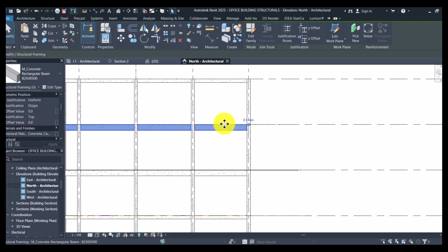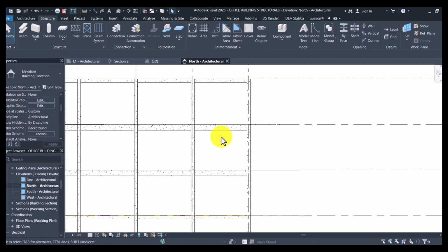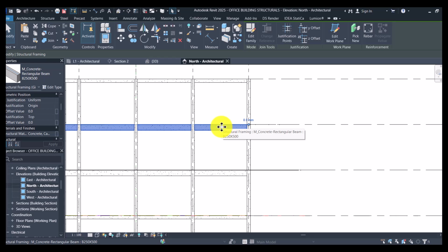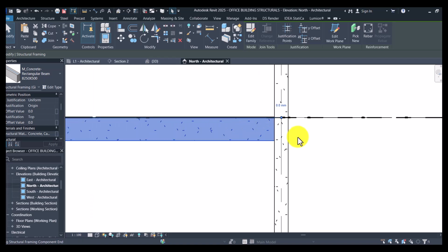However, for analysis purposes, we need to always first set these beams to be at center such that we are able to correctly export this model. Then later we'll take it back. Because we need the center lines of an analytical model to be coinciding, like the center should be in position to meet.